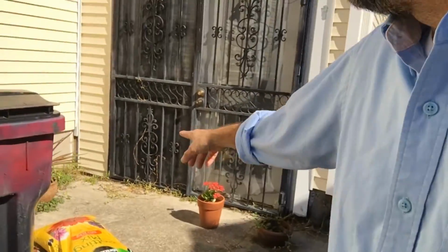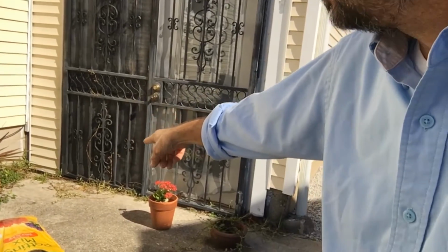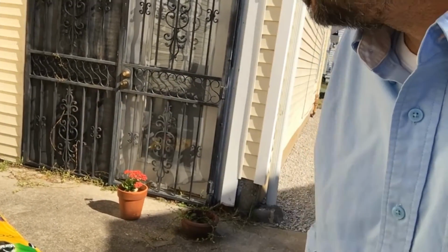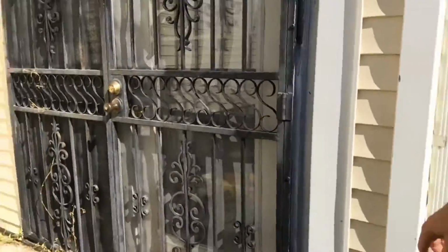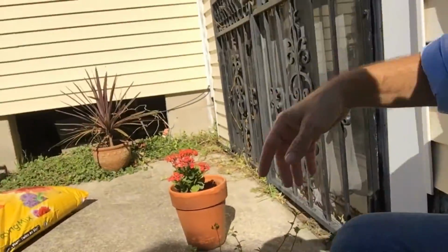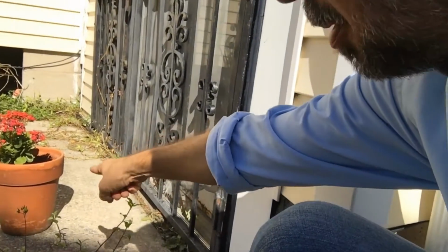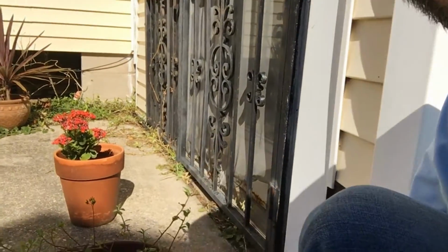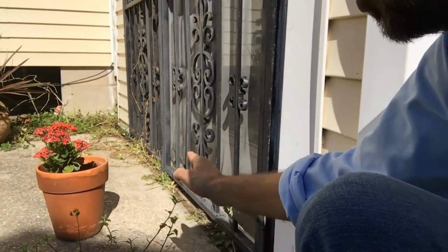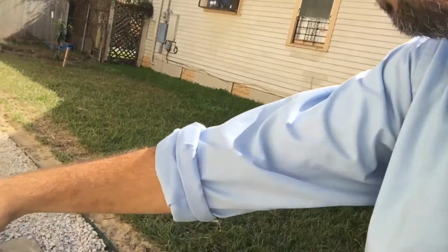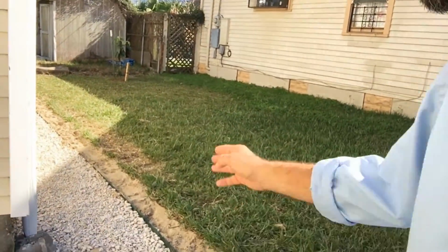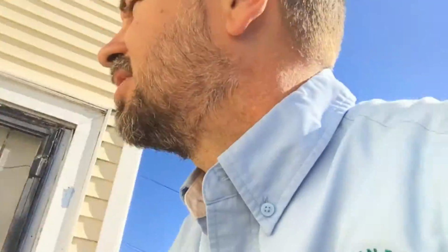Phase 2 would be for us to saw cut over here, the bottom of the concrete, this direction, along it. See it? Like from the pot. So imagine from the edge of that pot to the house. We'd saw cut that out, remove it, and tie it into the drain. It'd come over and tie right into the existing French drain and then exit where all the other stuff is exiting.